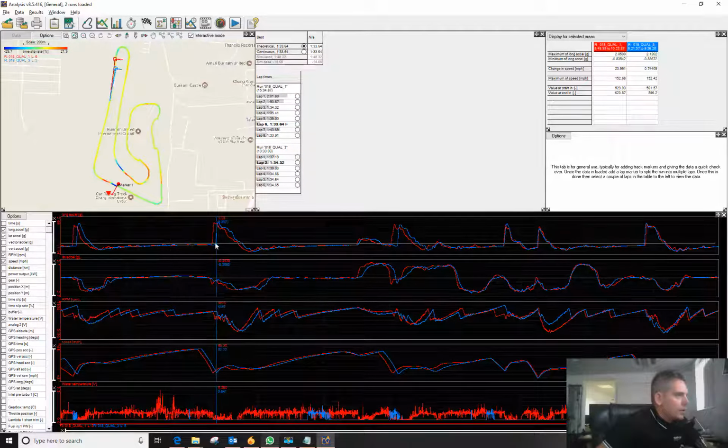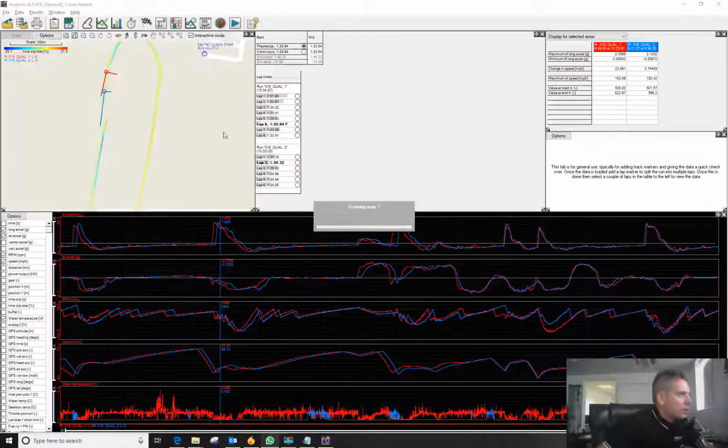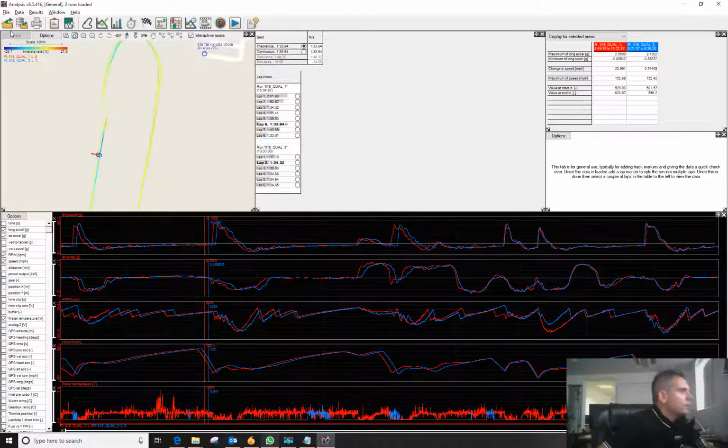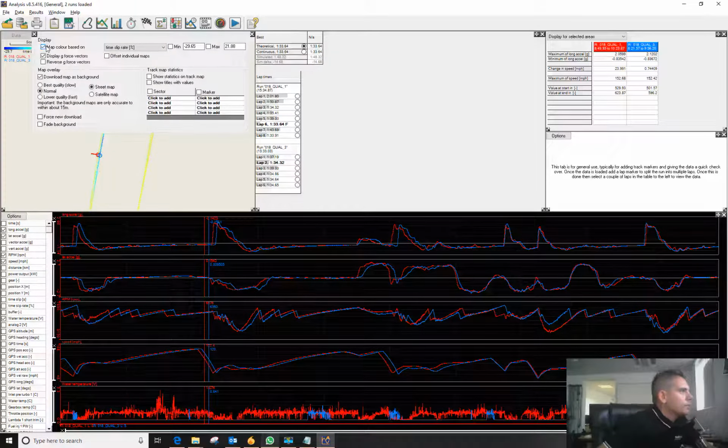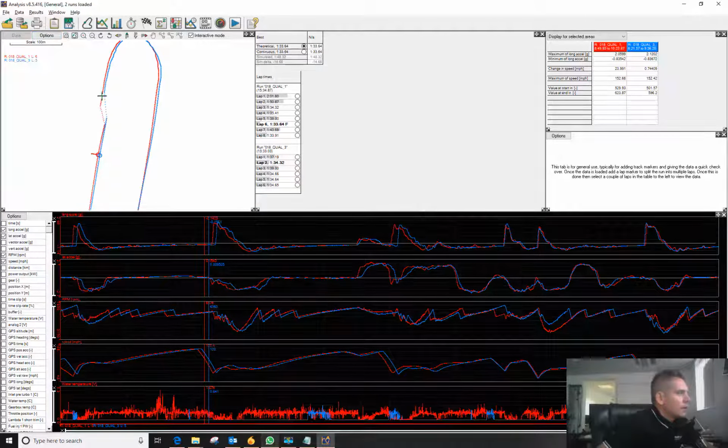so now here, look, above this line, this is longitude and acceleration. Above this line is accelerating and below it is braking. So here you can see in the braking zone it thinks it's accelerating. So what it actually does, let me just switch these off, is it messes up the track map.